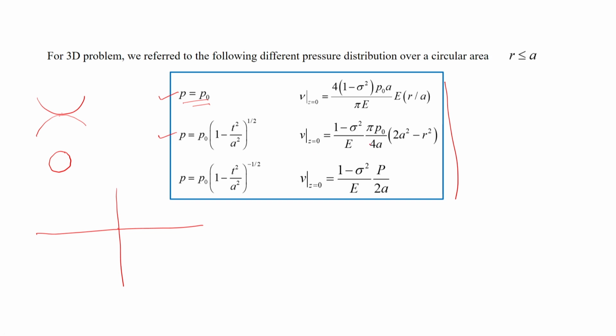And so we could easily relate them. We found that for the spheres in contact, the summation of vertical deformation of the two spheres can be written in this particular form. And so then we thought that the pressure distribution between two spheres is like this. So the results that we obtained from our analysis of loading on an elastic half space, we could directly use when these spheres were in contact. But there is a little bit of difficulty in using those results when cylinders are in contact. So I will briefly describe where the problem is.